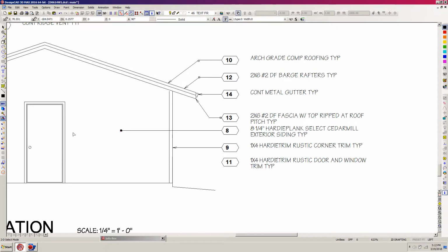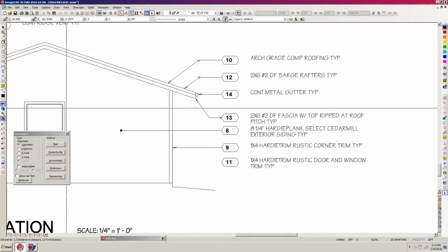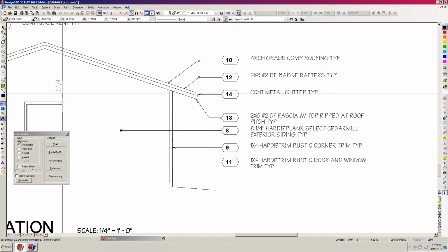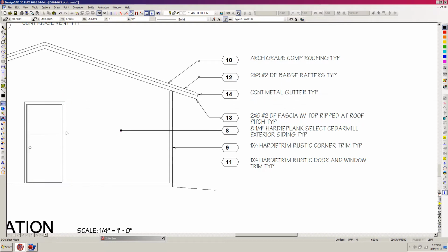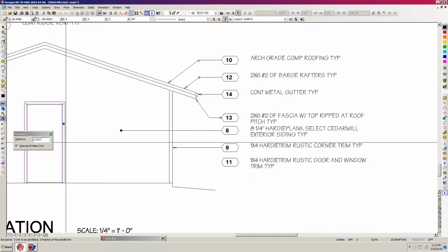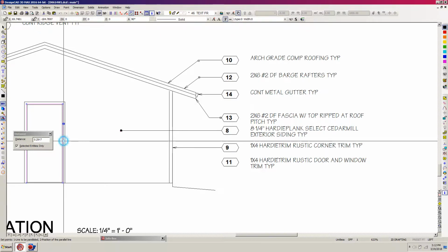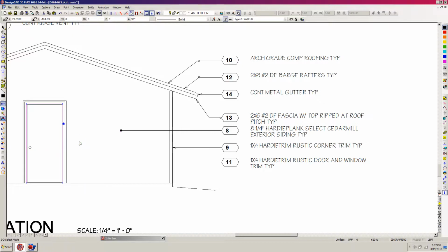And then for the door trim. Now, I don't think this is 3.5 inches either. Let me check it out with a dimension real quick. It looks kind of thin. Yeah, 2.25 once again. Okay, so what I'm going to do is click on this door line here and hit F2, and we're still at 3.5 inches or 0.2917, and click to the outside and pull it on out and click again, hit escape, click on the old trim line and delete that.